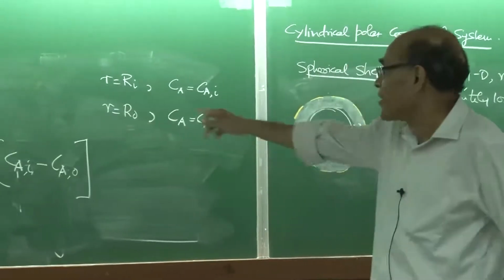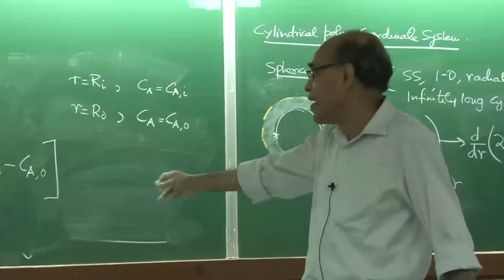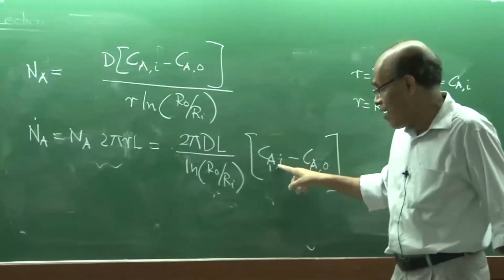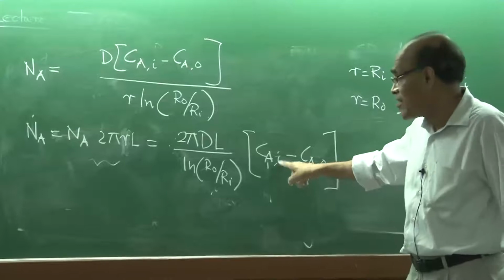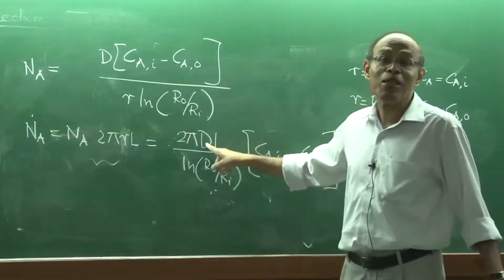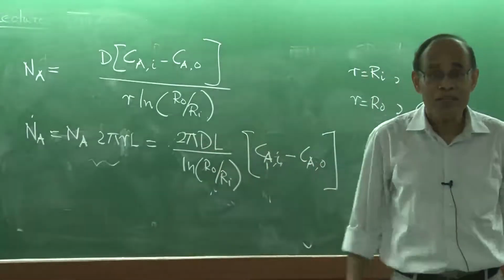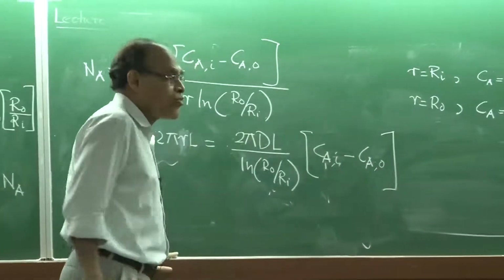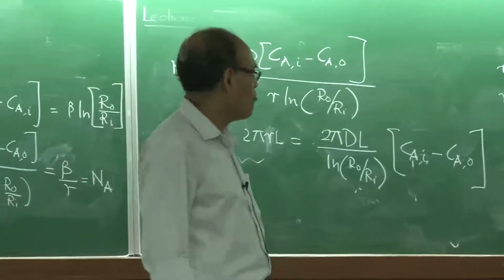and if the same problem is posed to you in a cylindrical coordinate system, then this is the formulation that can be applied. When you convert this to partial pressure, we will have the Sievert's law constants coming in, and that Sievert's law constant multiplied with the diffusion coefficient will give us, as you know, the permeability. So I think we will not discuss anything beyond this.